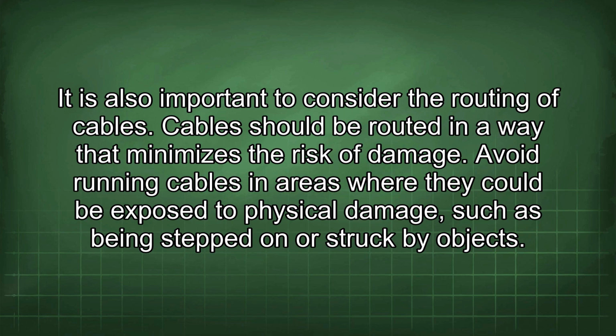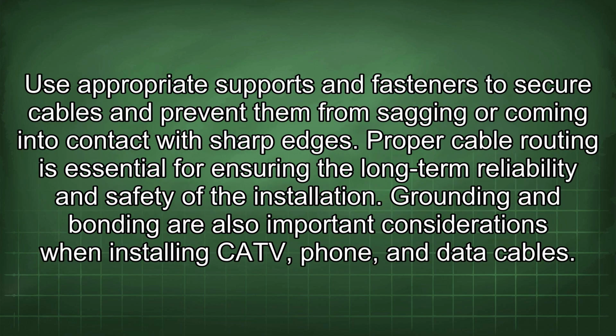It is also important to consider the routing of cables. Cables should be routed in a way that minimizes the risk of damage. Avoid running cables in areas where they could be exposed to physical damage, such as being stepped on or struck by objects. Use appropriate supports and fasteners to secure cables and prevent them from sagging or coming into contact with sharp edges. Proper cable routing is essential for ensuring the long-term reliability and safety of the installation.